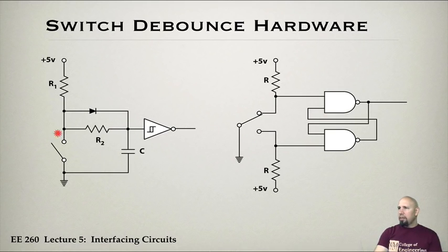What this does here is it provides a low-pass filter kind of situation. So this switch is touching, touch, touch, touch, but this signal here has been low-pass filtered. The basic idea is these contacts happen very quickly, and depending on the value of R and C, you can make this respond slowly to those taps.